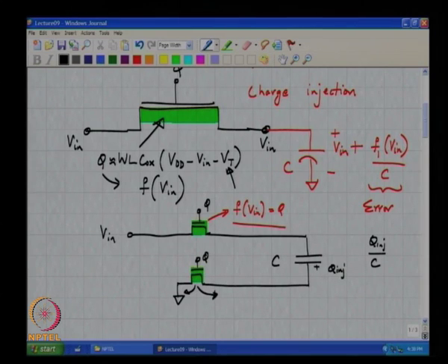All right. So, now if this transistor is turned off, this is the situation we have here. The top switch is still on, and we are getting ready to turn it off, and there is a charge in the channel which is non-linearly dependent on the input. Now, when you turn this off, what do you think will happen to this charge? Whatever we know or do not know about the dynamics of charge injection, one thing is for sure: if on one side there is an open circuit, charge cannot flow in that direction.